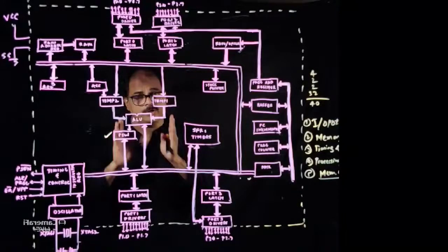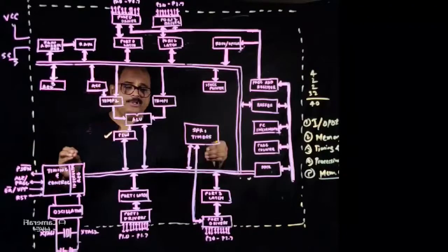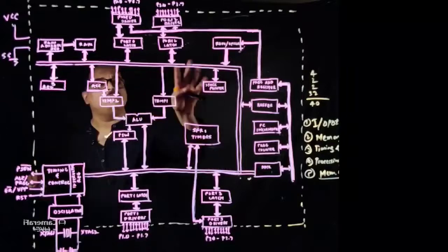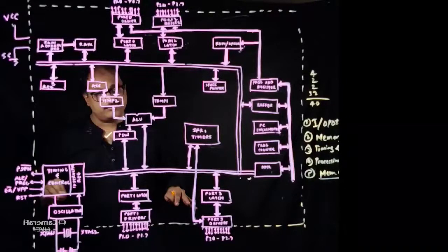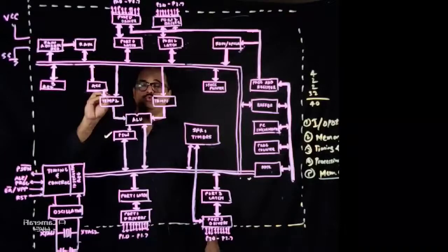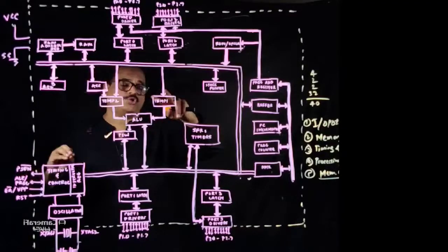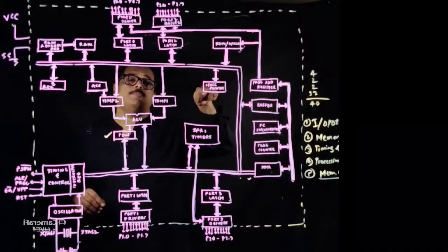You are going to decide where you want to store that data, any data. Obviously during the programming you will understand it better, but remember, any data that you want to store temporarily on the RAM, you have to use a stack for that purpose. There are some instructions like the call instruction. That call instruction uses this stack memory of its own. It is hardwired into the execution of the call instruction. Now the stack pointer points to the stack memory, the top of the stack memory.